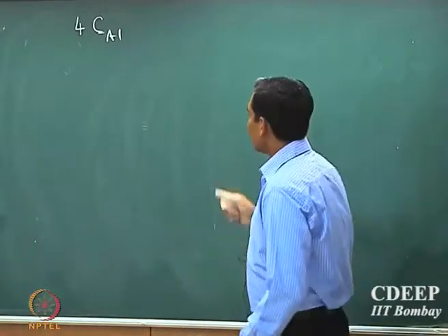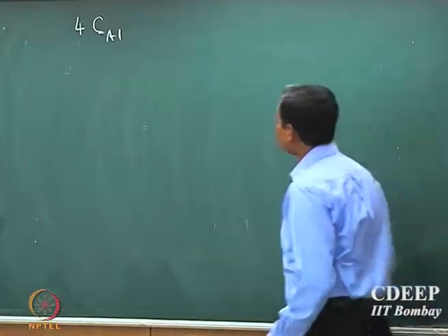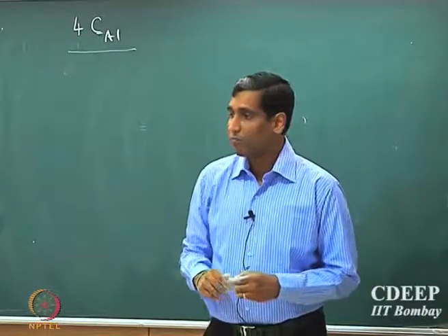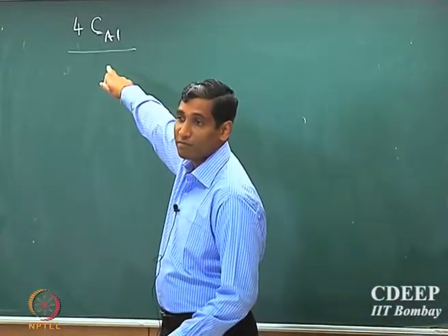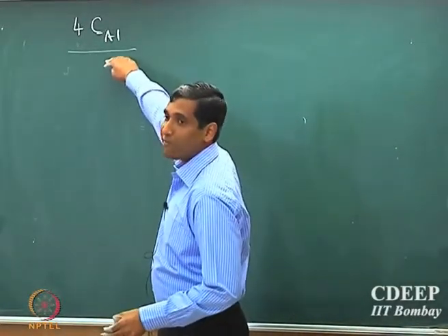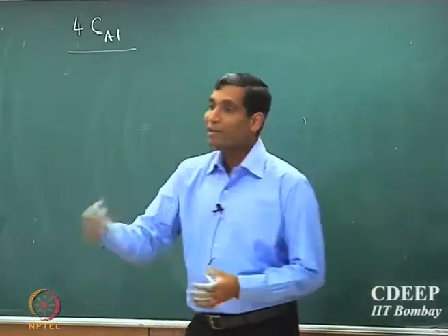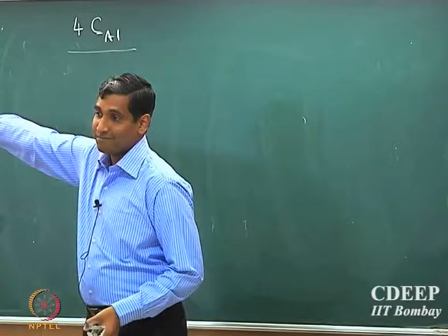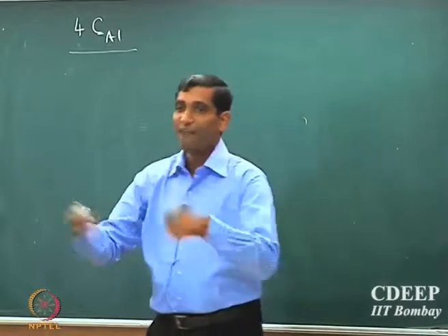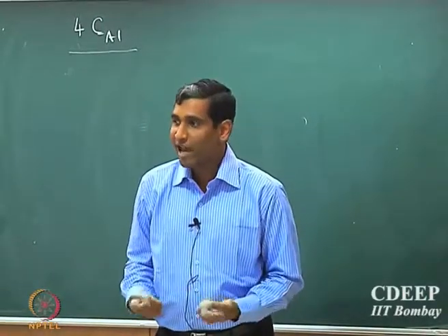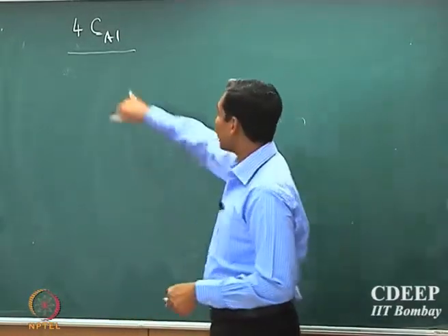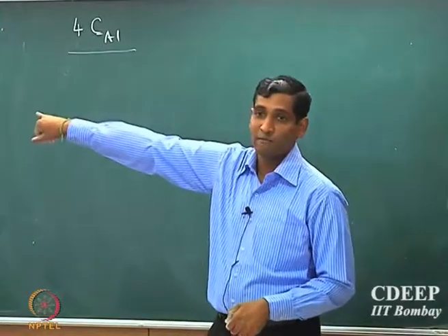Correct. So the first thing is that if you assume that the transport, the velocity effects because of the concentration change is negligible, right? So you can still have incompressible. If you have 4 times the species that is added, you can still, by tweaking the velocity, have a higher velocity flow, you can have gradients, you can play with the gradients du by dx and du by dy and still maintain incompressible fluid. Okay. So incompressible does not mean necessarily that the concentration does not affect the velocity.